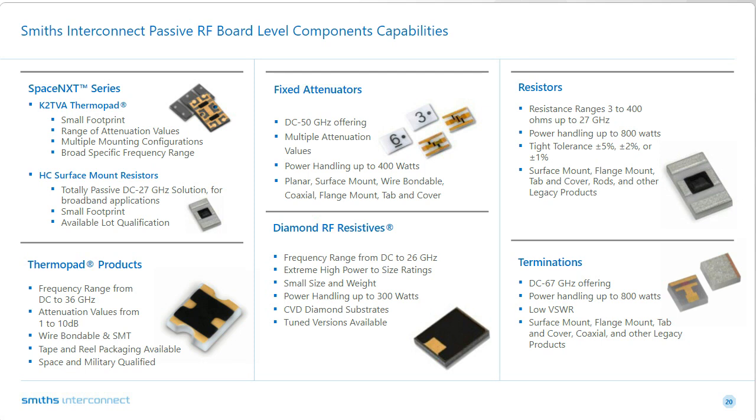So gentlemen, our first question for today: what are the most common surface finishes of the components intended for space and military markets? I can take that. Gold and tin lead are the most common ones for our space and defense applications. Pure tin or any alloys containing greater than approximately 96% tin is not suitable for space or most defense programs. This is due to tin whiskering, which has caused satellites to fail and other reliability concerns in the industry.